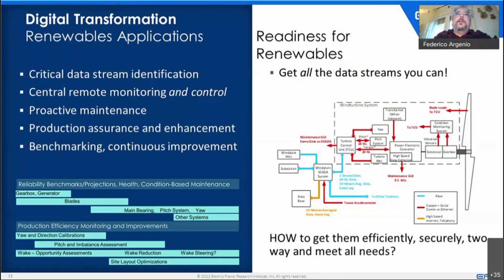Then all of the data quality in post-processing is performed by our tool. For example, we check if the data are out of certain thresholds. We check if the data are missing with respect to the number of occurrences that you must have if you analyze 1 hour of minute data for power output of an inverter.